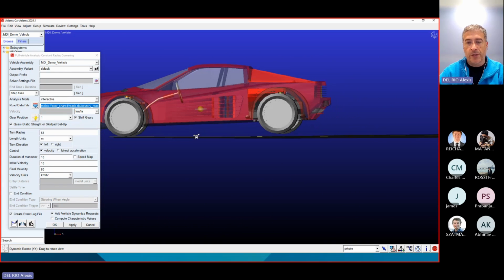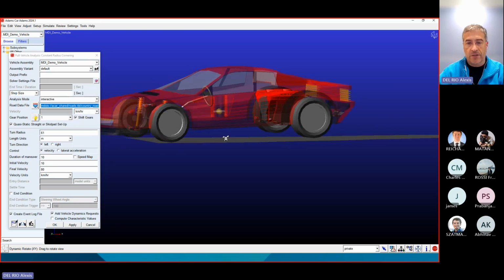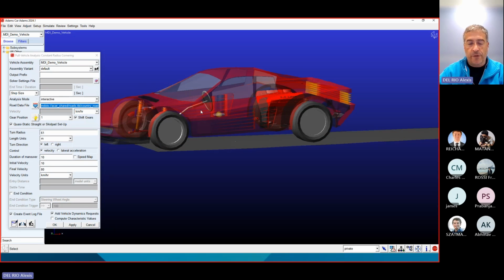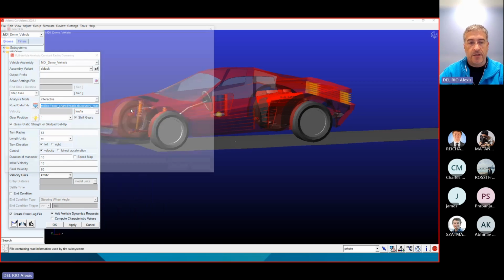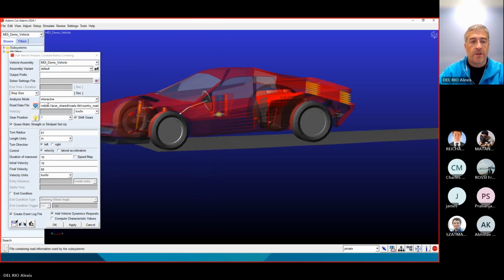So once you put it in the right position and rotate it, you will notice that the vehicle is in the air. If you try to run this event like this, it will fail because the vehicle will try to land on the road. It will not have enough iterations to finish, and it will fail. So then there is this reposition file.